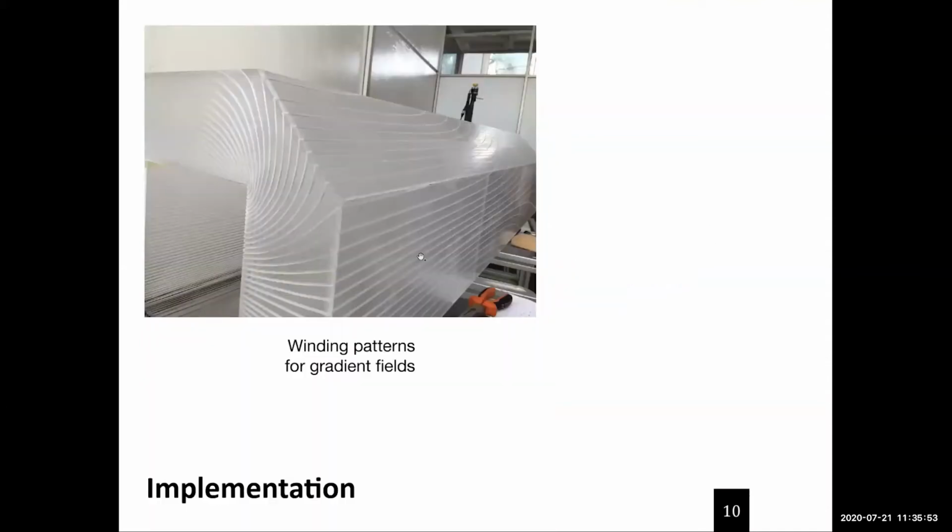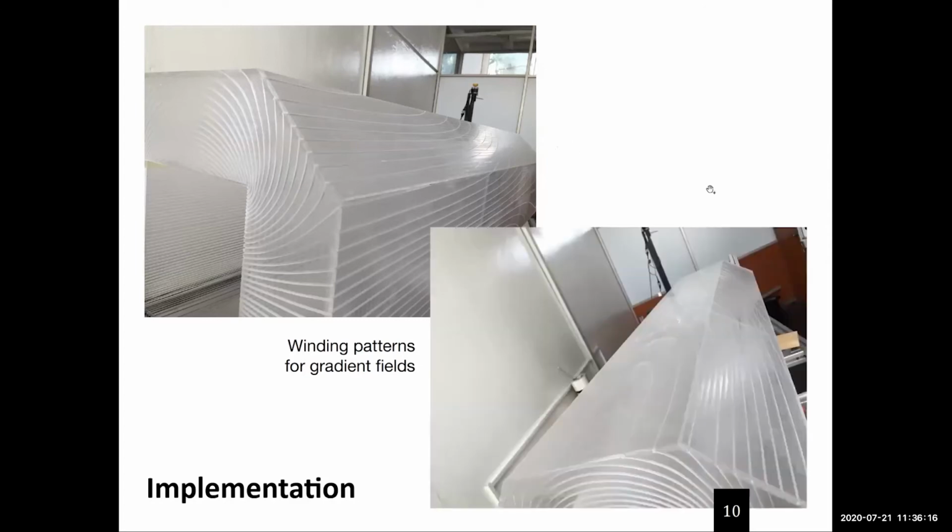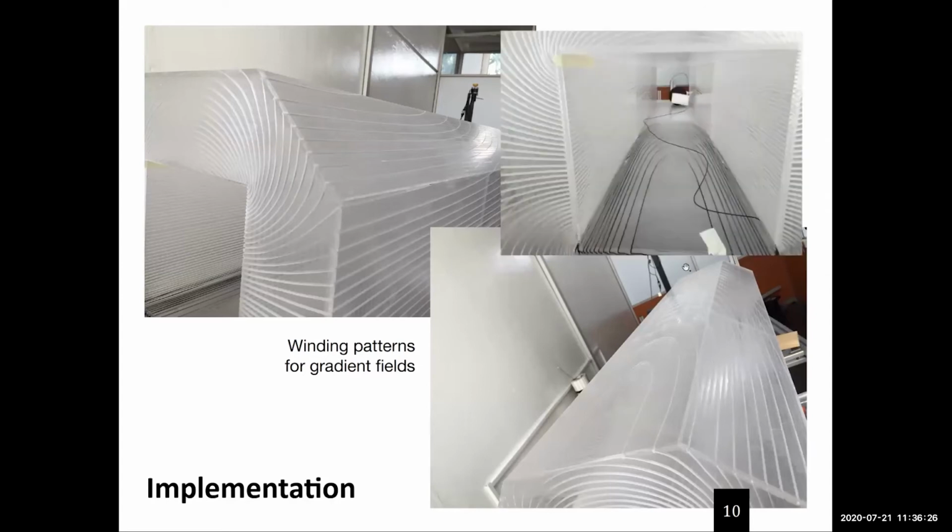This is showing the same, but for the output coil, which is the one that needs tapered magnetic fields along the length of the coil. So you can see how the windings start turning around before they go to the other end of the coil. You can see that here in different pictures. So we have a higher density of windings in one region and less density of windings in another region.